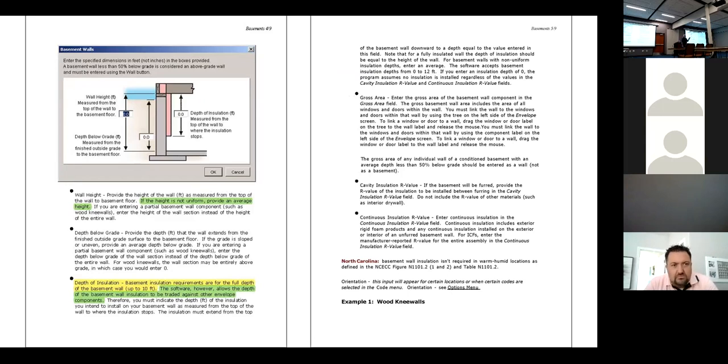I've had REScheck reports turned in to me that just barely passed, and they said we have 8-foot walls, 8 foot of insulation, and 8 foot of dirt on the outside, which means they were buried right to the top of the foundation. And that's what they did to get it to pass. When you put the 18 inches exposed, it didn't pass. And it's because we're exposing not the foundation to dirt, but to outdoor cold temperatures.